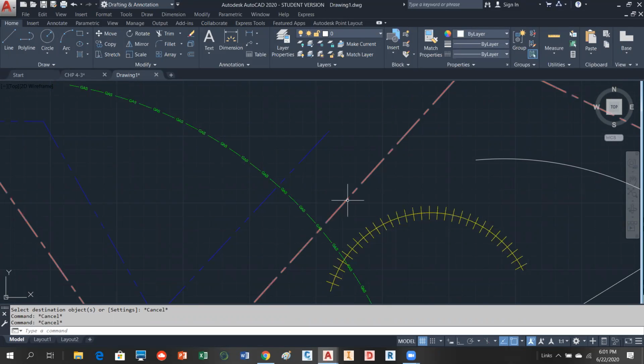You'll notice these have a spacing on them right here. So that might be a 1/2 inch and then a 1/2 inch space, and then maybe an inch object and then a 1/2 inch and a 1/2 inch. That spacing can be increased or decreased basically by multiplying a line type scale on it.